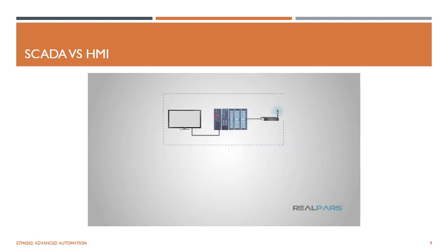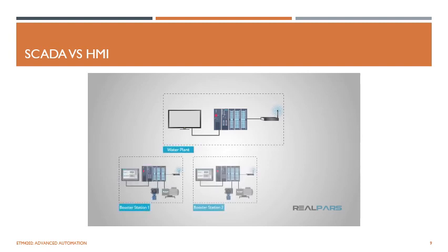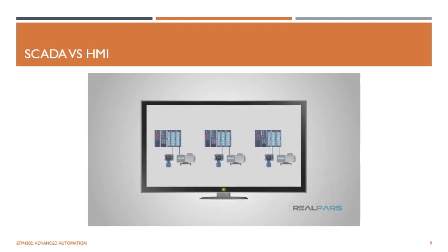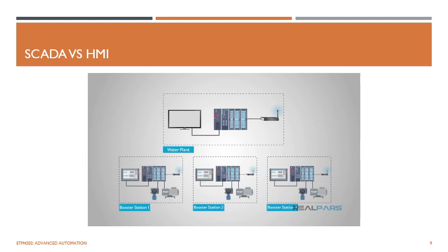So let's talk about a common use for SCADA that I have personally encountered. While working for a water and wastewater treatment facility, I encountered a SCADA system. The HMI was located at the main water plant building. This HMI was connected to the main SCADA unit at the water plant. Each booster pump station within the water district was represented on the screen. At each location, there was a PLC that was connected to some sensors to monitor water flow, pressure, and other things, and it was able to run and control the pump itself.